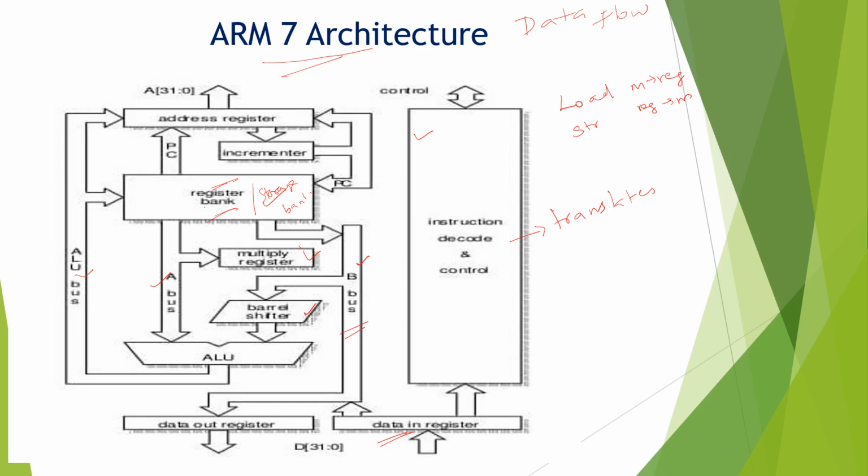And see here, in the instruction we have seen two source registers for operand 1 and operand 2, and one destination register. So operand 1 contains the first data, operand 2 contains the second, both undergo the opcode process, and the result will be stored in the Rd register.